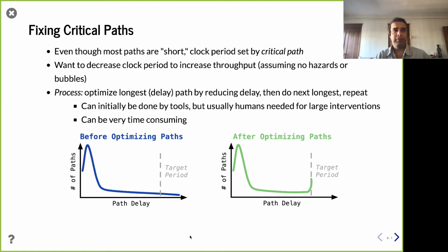If you're able to go easier and say, you know what, we can go at a gigahertz, 800 megahertz, we don't need to push it that hard, life gets a lot easier. So you might see, for example, that a lot of academic chips that have been taped out run at a gigahertz, right? Optimizing enough to run at 2 or 3 gigahertz is theoretically possible. It's just a lot more engineering effort, and for academic researchers, that's maybe not worth their time, right? So it's easy to get something running, but to really trim this long tail and get to a certain period, there's going to be some time there.